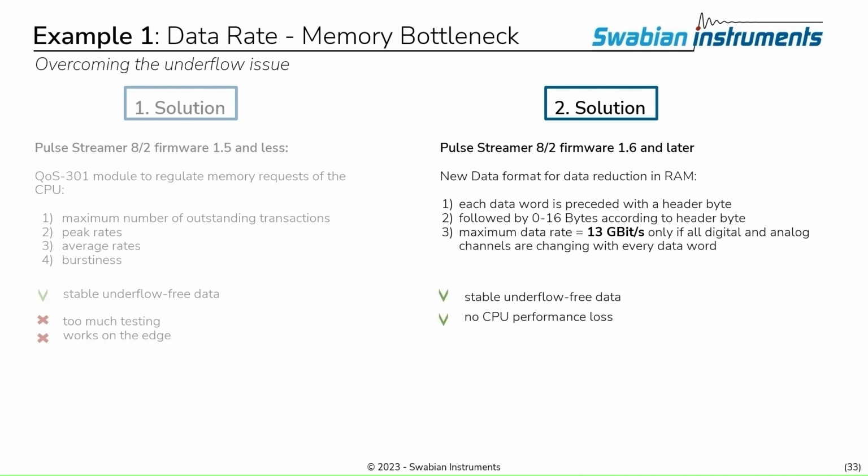With shifting the whole address calculation for memory access from the CPU side to the FPGA, which wiped out vast data traffic between CPU and FPGA, we no longer need CPU memory request throttling even in the unrealistic theoretical maximum data rate situation.